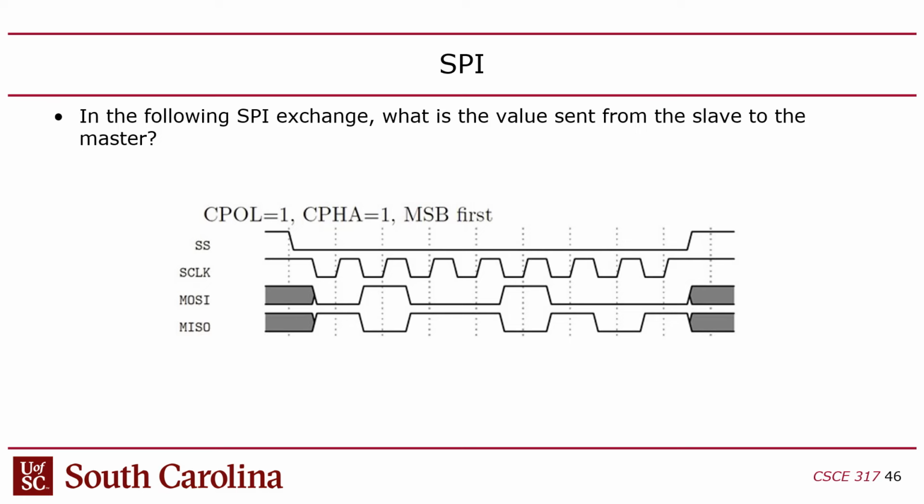You might not know, but you can get those timing diagrams if you have an oscilloscope with you. If you don't, go to the datasheet and read what CPHA is. Yeah, that's a good point. I'm assuming that you can figure it out with the timing diagram, which in this class I'm going to give you, but in practice, yeah, you'd need an oscilloscope to actually see it.